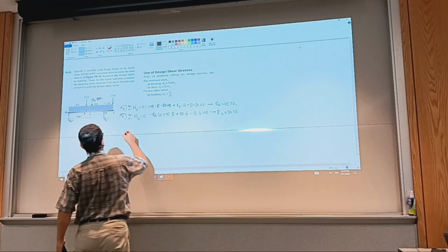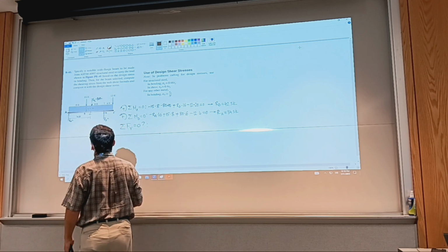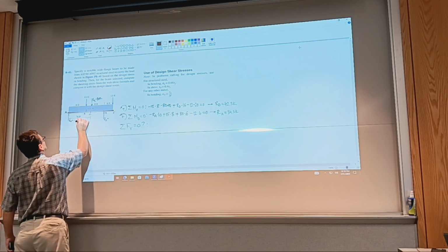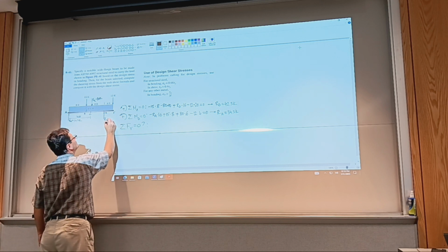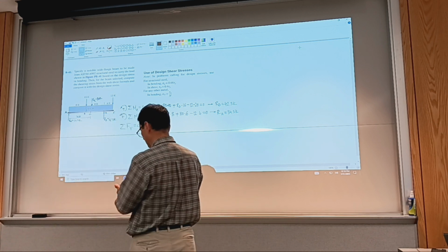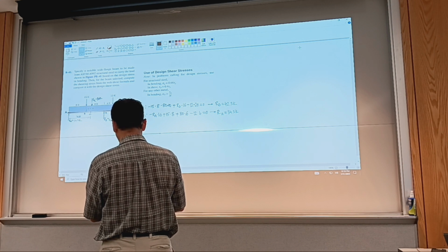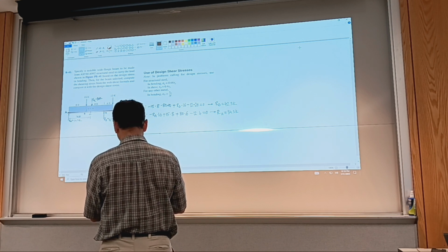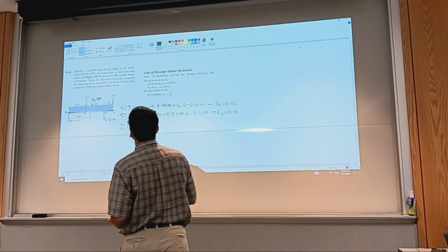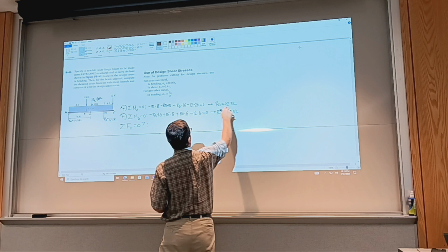All right, so verification, sum of forces in the vertical direction equals 0. Is it indeed? So I said RA 34.5 K, and this one is 42.5. Okay, so we have 34.5, negative 15, negative 80, plus 42.5, minus 12, and it's not equal to 0. So what have we missed? I expressed doubt about the first one, so let's see again.